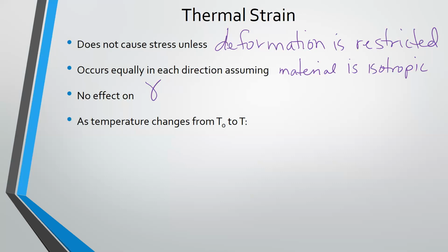So let me clarify a couple things. There will be stress because it's wanting to expand in all three directions, yet it's constricted in two. So there will be stresses. Now, to get more exact into your question, near the attachment there will probably be some stresses because technically speaking, that beam is also going to want to constrict in the cross-sectional dimension, and where it's fixed, it will not be able to do that. But when we get far away from that fixed point, there shouldn't be stresses.